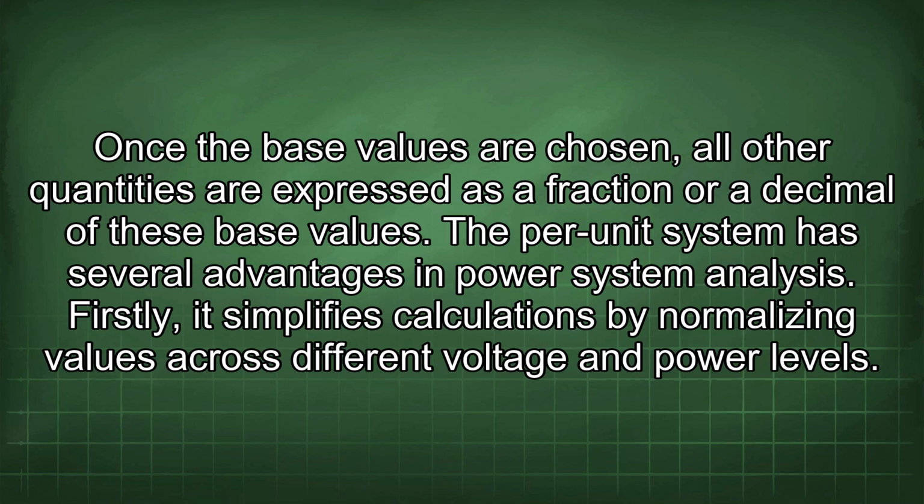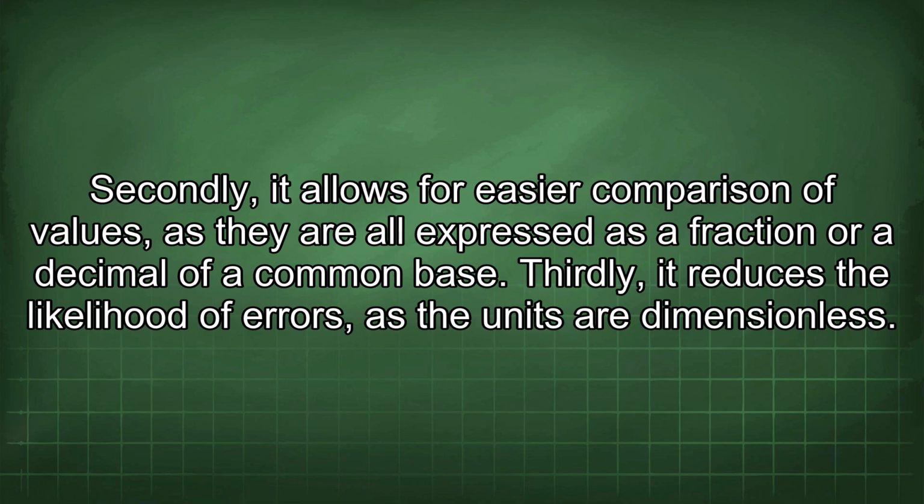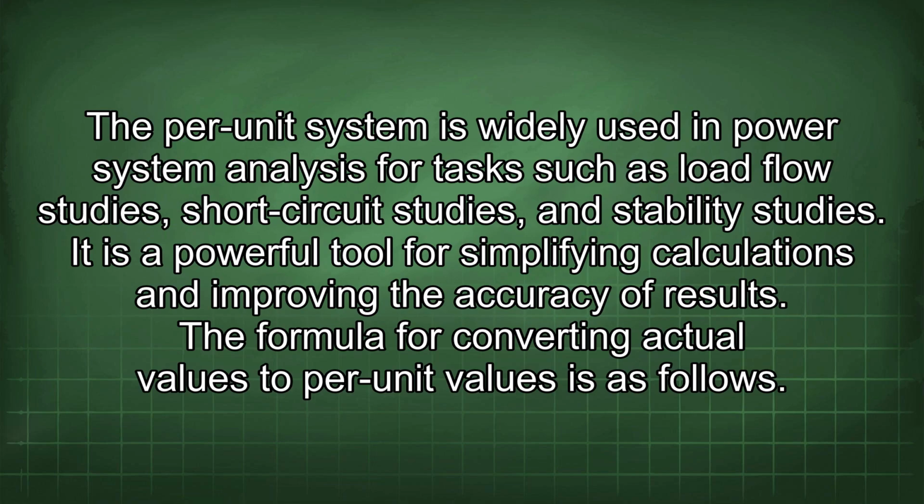Firstly, it simplifies calculations by normalizing values across different voltage and power levels. Secondly, it allows for easier comparison of values, as they are all expressed as a fraction or a decimal of a common base. Thirdly, it reduces the likelihood of errors, as the units are dimensionless. The per unit system is widely used in power system analysis for tasks such as load flow studies, short circuit studies, and stability studies. It is a powerful tool for simplifying calculations and improving the accuracy of results.